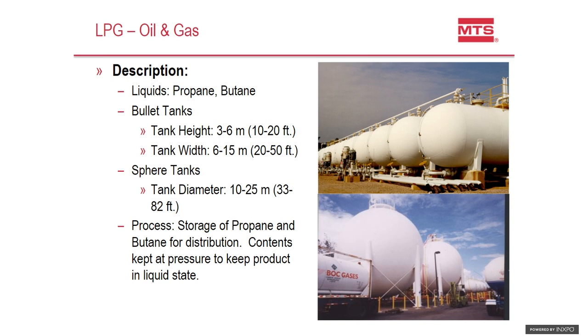So when you're looking at a level transmitter for this, you want to be able to take a look and understand what is the field service, what's the repairability of the device. You do not want to have to take one of these tanks out of service just to do a common repair on a device. So you want to find a technology and a specific manufacturer that allows you to replace, for example, your electronics due to a lightning strike. If you have to take the tank out of service to do that, then that's not going to be a very good fit for this application.